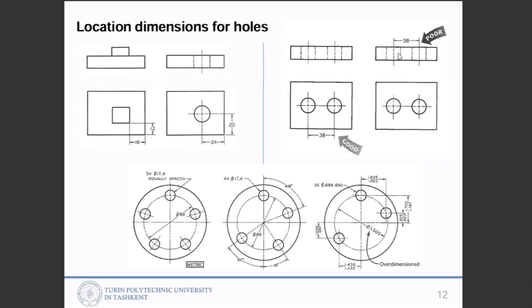So you should avoid defining dimensions in a view where the features are hidden. Do not add dimensions to hidden features.